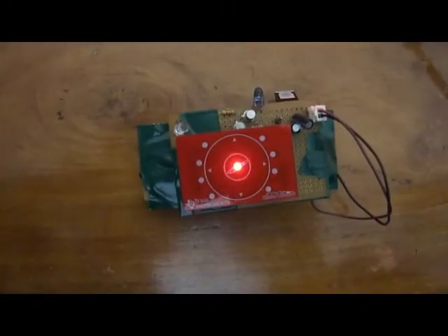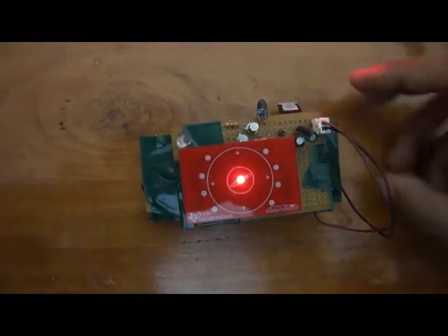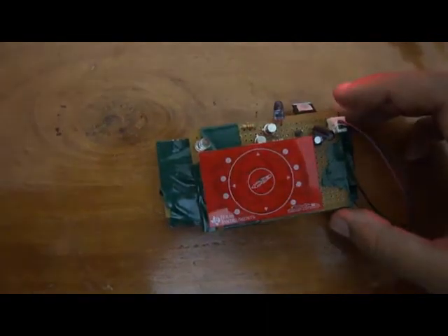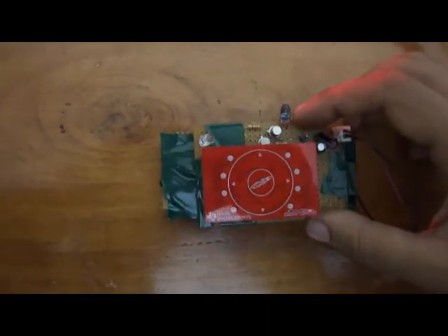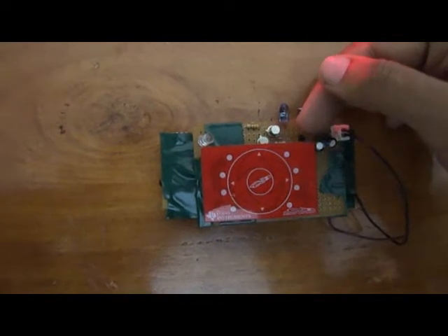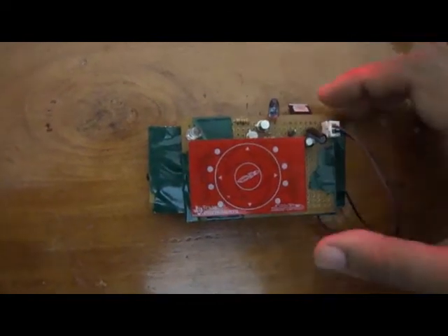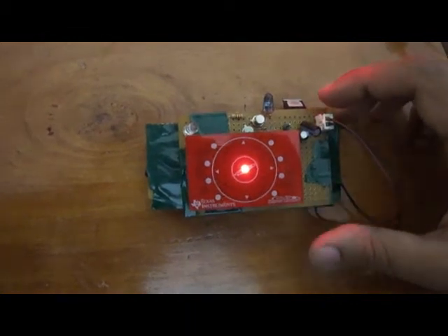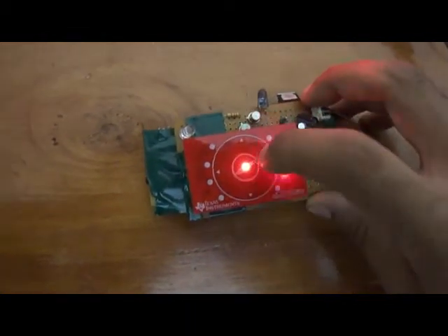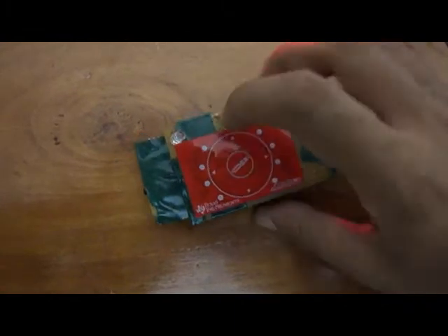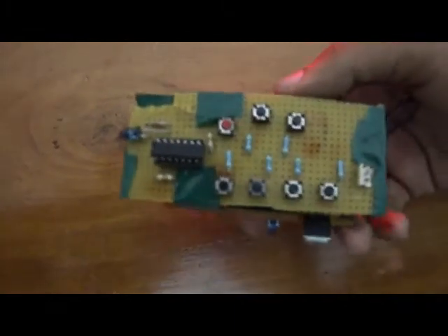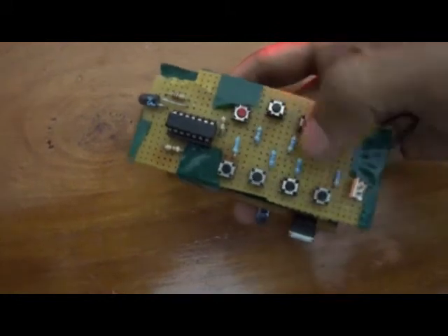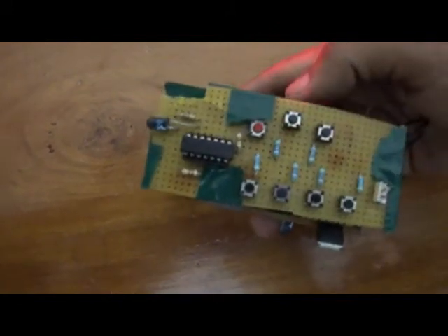This is the basic remote control that we've built. It consists of a capacitive booster pack that we sourced from TI and an IR LED. Under the booster pack is actually an interfacing microcontroller, in this case an MSP430G series 2452. As an alternative to this remote, we have also provided a basic remote which uses another G series microcontroller and buttons instead of capacitive touch to reduce power consumption.